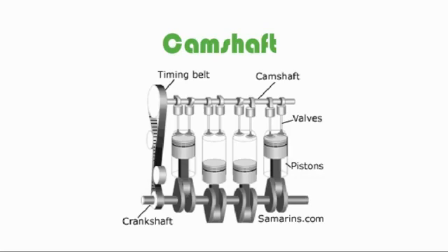This makes them not only critical to the operation of an engine, but because the opening and closing of the valves must be carefully and perfectly synchronized with the movements of the pistons, they also have a drastic effect on performance. To ensure this timing, the camshafts are connected, via a timing belt or chain, to the turning of the crankshaft, which is directly moving the pistons inside the cylinder. Moreover, the shape of the cams themselves is also carefully crafted to control the speed at which the valves open and close.